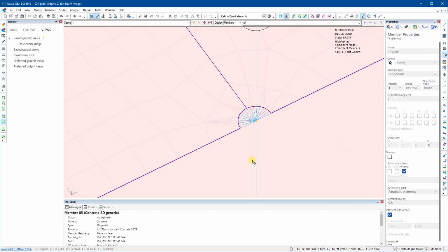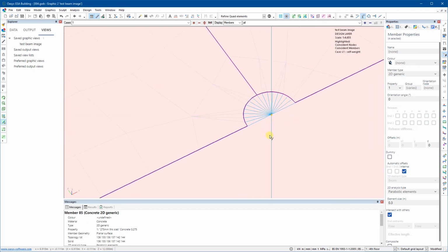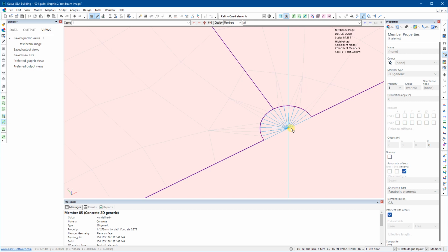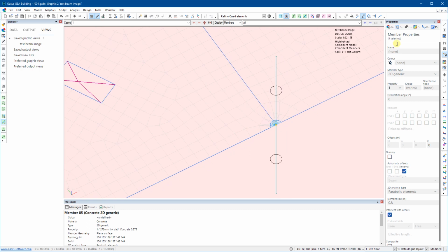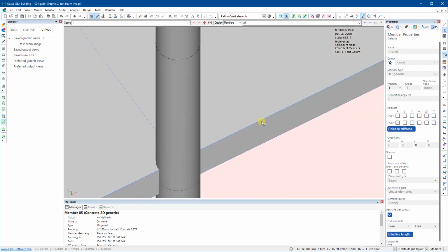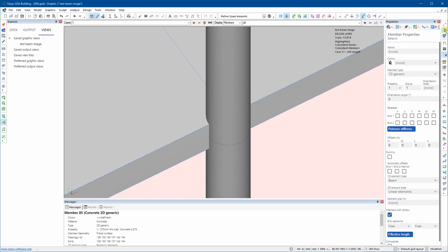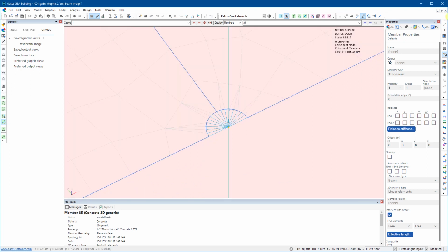Well, I wasn't expecting that. Anyway, what this is showing is that we've got the node that the stick is connected to. This is then the size of the column itself, so a circular column, as you see there, going through the slab, as you see. And what the software has done is essentially give you a set of rigid links or rigid constraints. And again, I discussed these in the lecture.